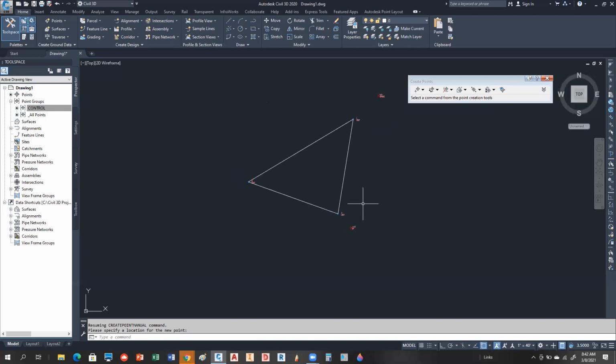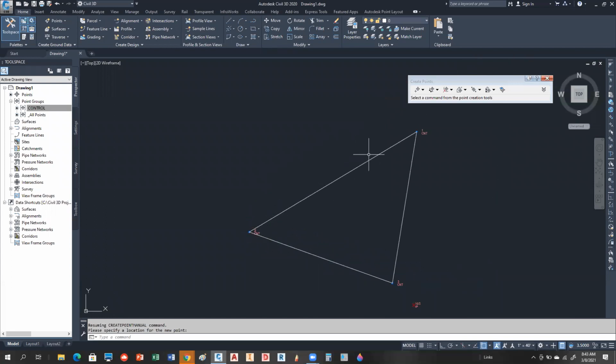How are we coming on that? Is that working for everybody? Yep. Okay, so we have one more control point to put in here. And then we're going to set up another point group. So I'm going to occupy 2, backsight 1, and I'm going to use the information that I have for that one. Okay, so that's going to be 105.